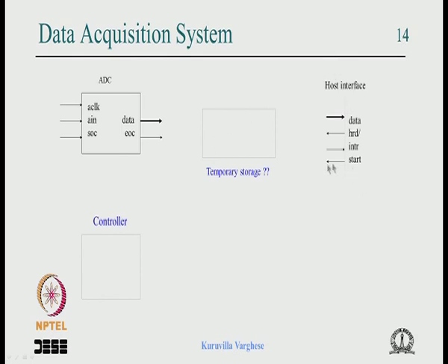The host will give a start signal to start all operation, and then we continuously keep on converting and putting it to the storage. When the storage is becoming full, the system will interrupt the host, and the host will read the output of the storage using this host read signal. So that is the basic idea.